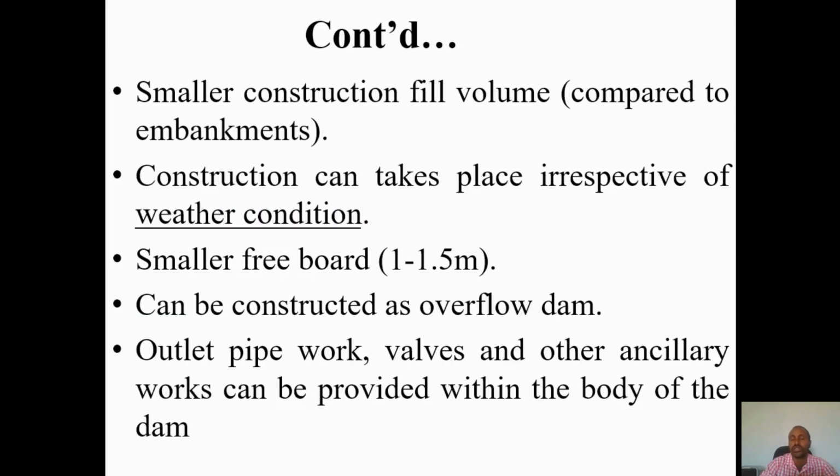This is also an advantage compared to embankment dams, because in an embankment you need huge transportation of fill material. But for a concrete dam, since it is narrow, the construction fill volume is smaller, and construction can also take place irrespective of weather conditions. During the rainy season, you can proceed with your construction. After rain, no problem.